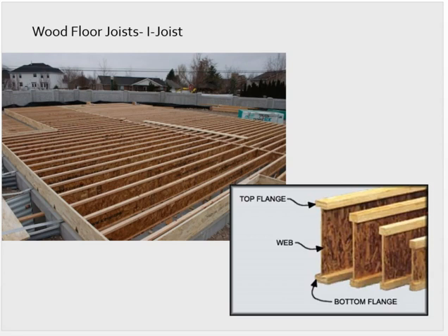Okay, here we have I-joists. So we talked about this product quickly. We have the OSB, kind of the strands of lumber all laminated together, that form the web, and then typically a solid piece for the flanges at the top and the bottom. Very light. One carpenter could pick up a beam this big, very, very light, and then there's a solid dimensional 2x here at the rim to secure them all.